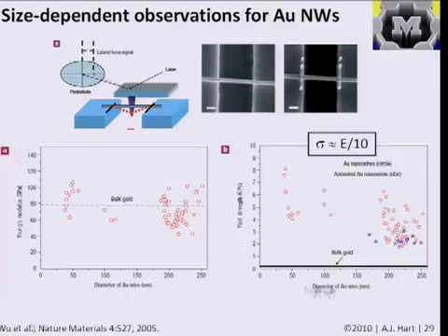However, when they looked at the strength, specifically the yield strength at which the material started deforming plastically, they found a really interesting trend. First, the strength of these nanowires was way higher than the yield strength of bulk gold. Gold is a pretty soft material. You hear about, you can bite into it and see if it's real gold because it's soft, because you'll see your tooth mark in it. Well, its yield strength is way less than 1 GPa.